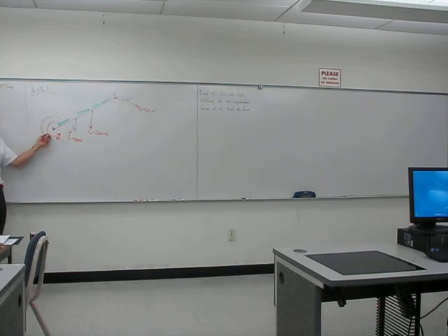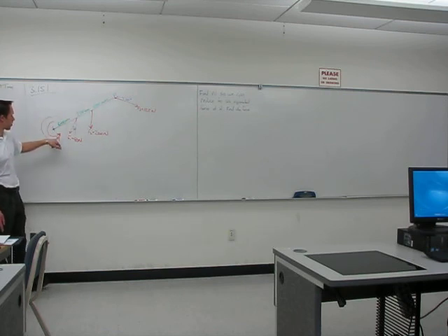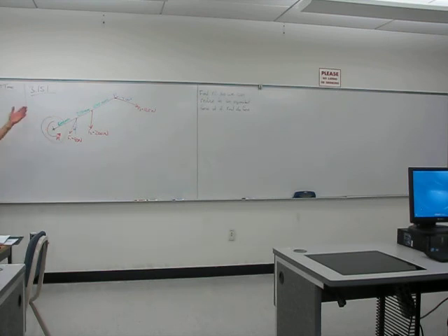Well, they happen to show it down here at point A. So just remember that moment vector represents a force couple that's applied somewhere on this rigid body. And for those 2 forces in the force couple, if we found their moments about any point, we would always get the same result, and they've called that M. They just happened to show it down here at the point A. They could have shown it at point B, though. Okay? And it would have been just the same.